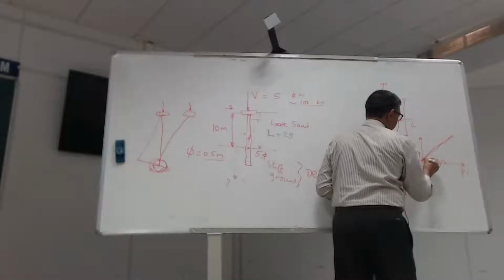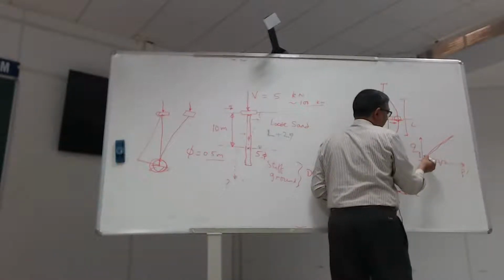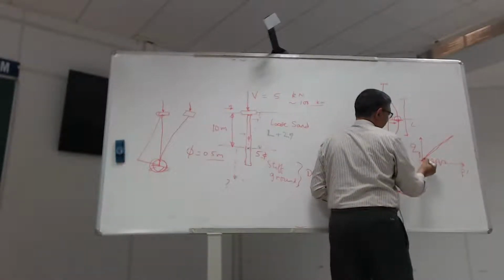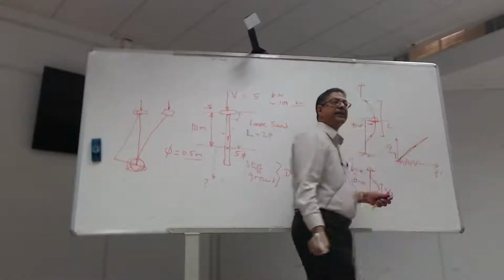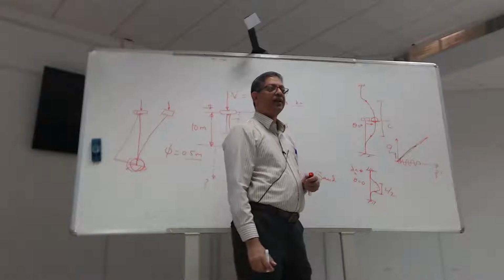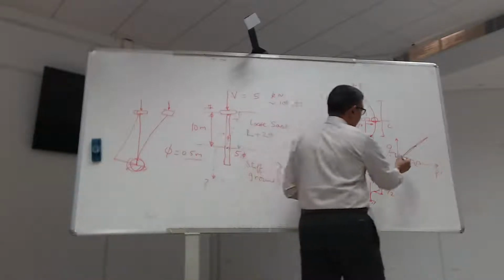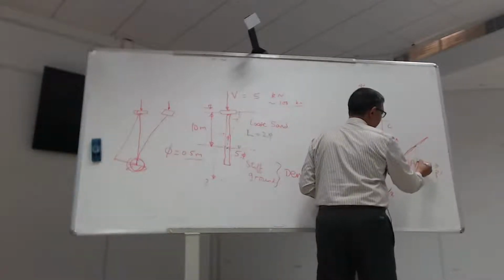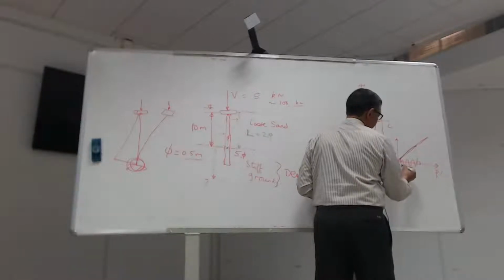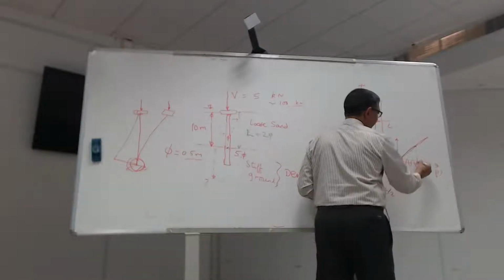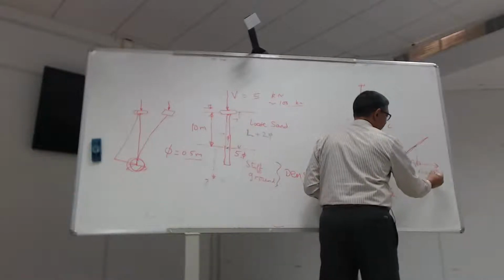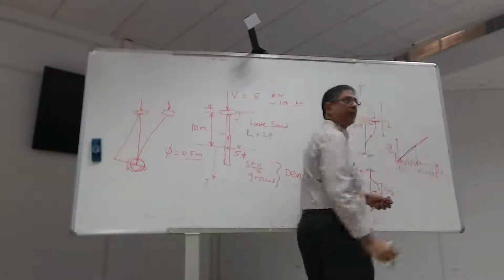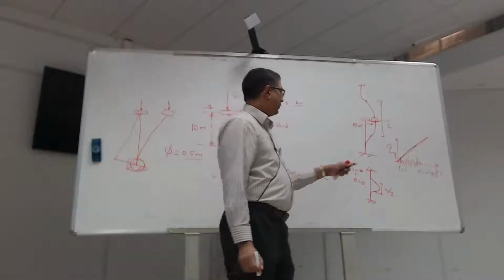And you're asking me to go up this way, and I can't go that way. I have to go along the critical state line, maybe up to here. If it is going up here, that means my p' from being approximately 0 here is going to be some value, x kPa.